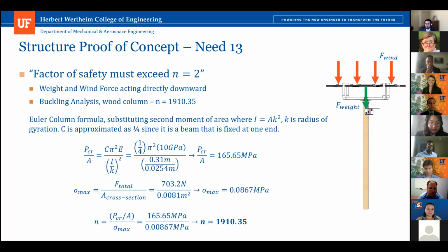And then I would just be concerned with how well the wood post would hold up over time. I know Nevada's got very dry air, but even pressure treated wood tends to absorb moisture over time, and that can lead to problems. So you're talking about long lasting. I'd question how long those posts would hold up over time. Other than that, great job.